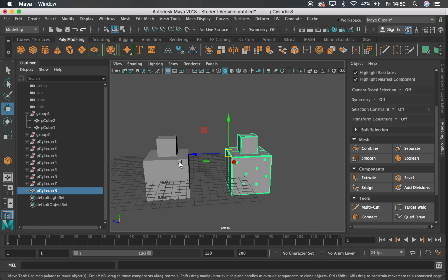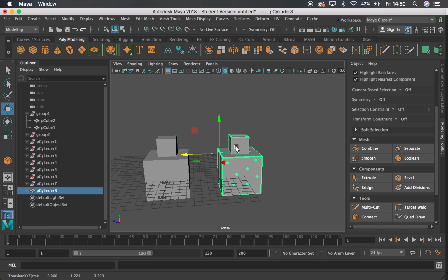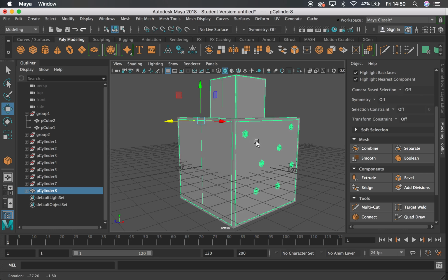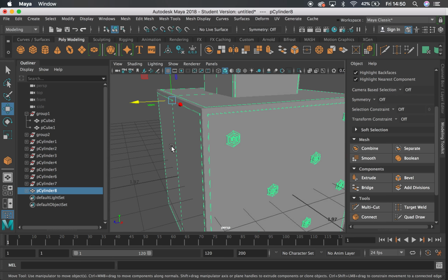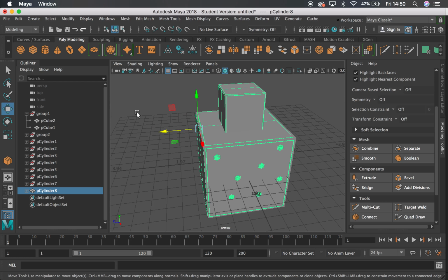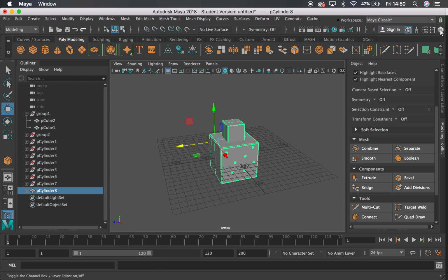So now that should be, if I hold D and snap, if I just move the whole thing, so everything's moving together, so that's why I parented it. If I hold V and now snap it in line with this one, they should perfectly overlap. So that flat face there, I've snapped it in line with this vertex here on this axis. Okay, nice.